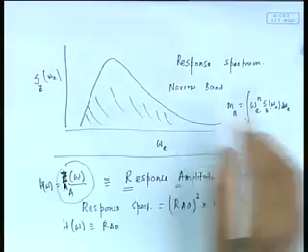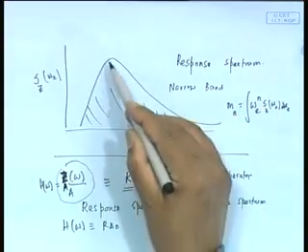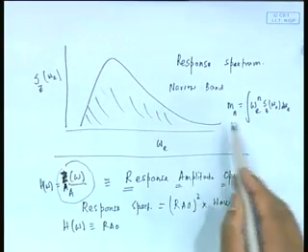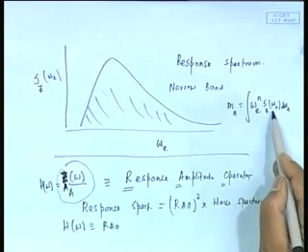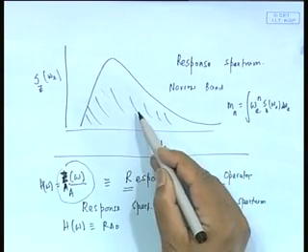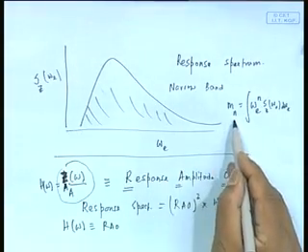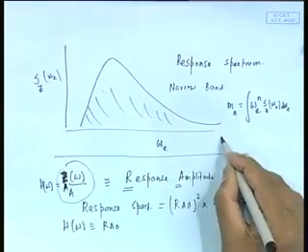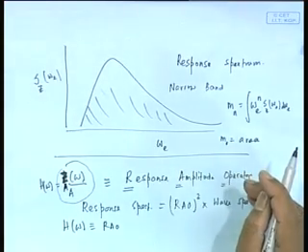So, now, with that clarification, let us look back at that. Let us take an nth moment of this graph. It will look like this: Mn is the integral of omega_e to the power n, S_z of omega_e, d omega_e. Now, since it is a narrowband spectrum, all properties of statistical importance are connected to these various m's. M0 is going to be the area, and in fact most people here are interested in the absolute value, the amplitude, not the time period, how much it is rolling, etc.